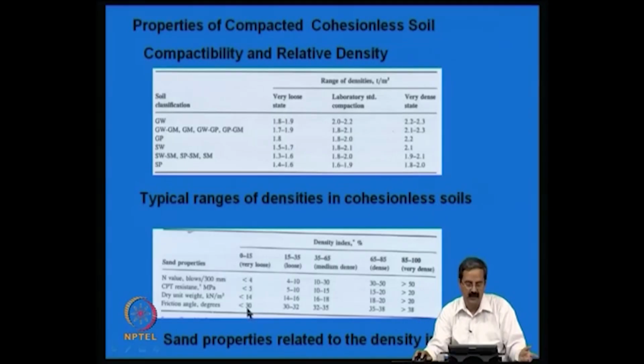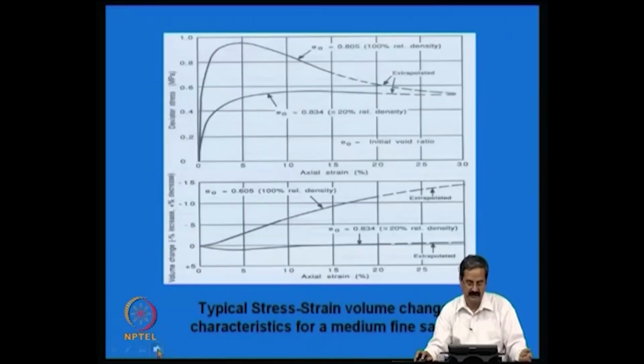Based on this alone, you may tentatively suggest a few things, that at this particular site the compaction was maybe not good. Or you can say that since it is a well graded gravel, the density should be in this range and not in 1.8 to 1.9, because I expect that there is good compaction. So, like that one can make some observations and comment on the results.